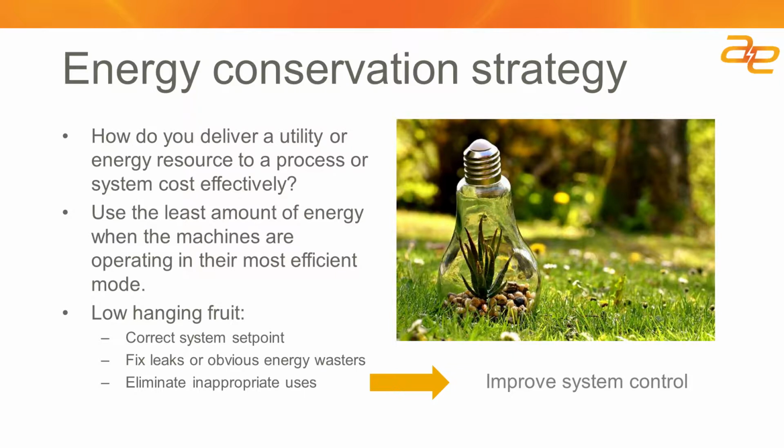Most facilities will do this, and they'll address what I'll consider the low-hanging fruit. They've often gone through the necessary engineering studies to develop the correct set points, so knowing what pressures you might need to operate, what delta T in your chilled water system you might need to maintain in order to maintain certain temperatures within your environment.